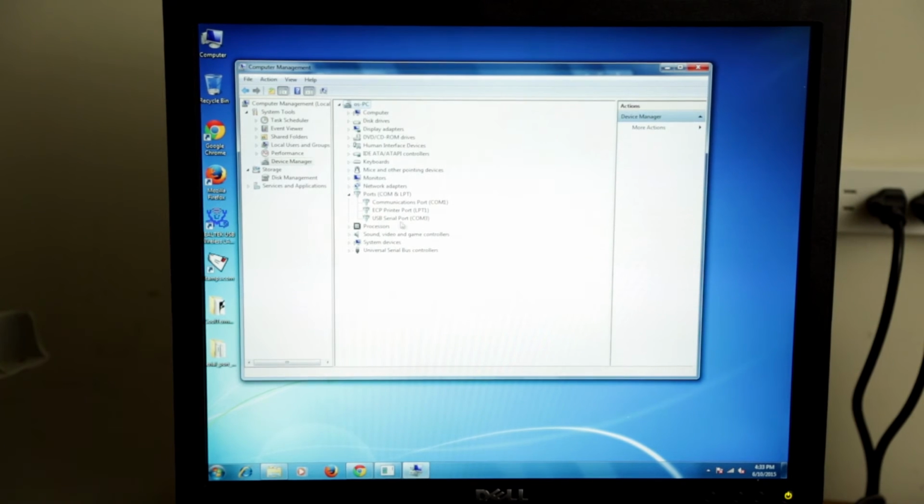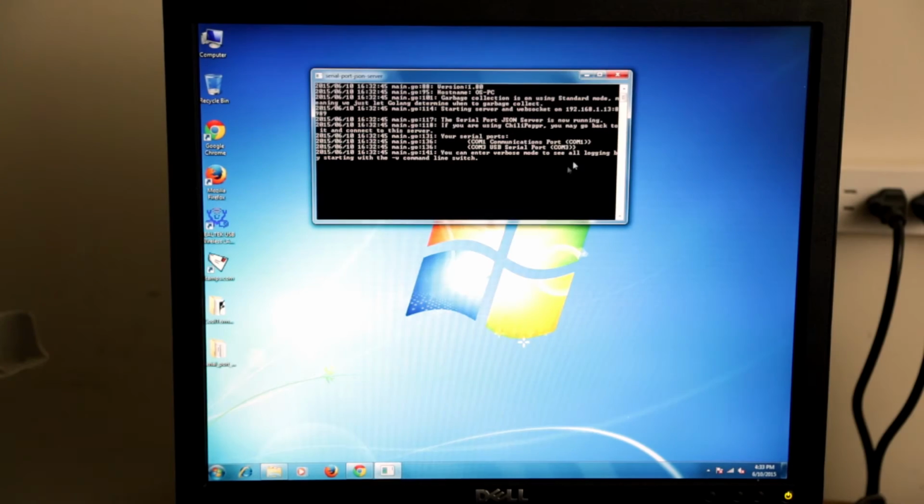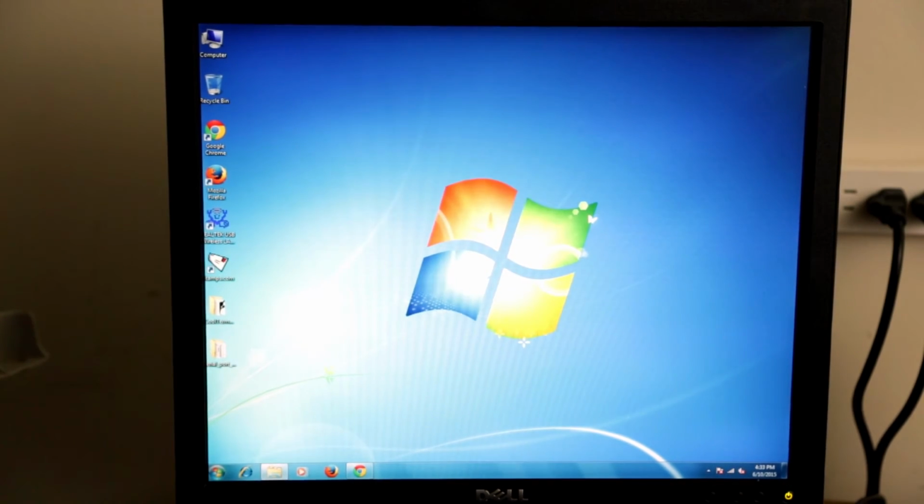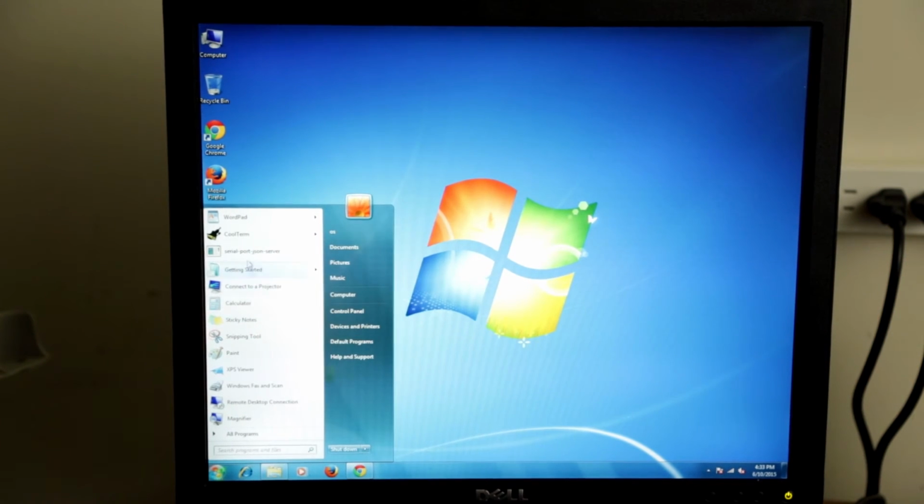It'll repopulate that list and show that something's missing here. We've got COM1, LPT1, and COM3 just went away. So what could COM3 be? Let's turn it back on. It repopulates our list, and we know that the TinyG is on USB serial port COM3. All right, so we've identified that. I'm going to shut that server down and rerun it because I know it's going to cause a problem.